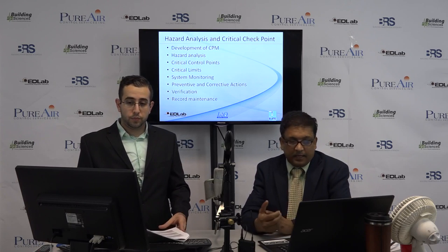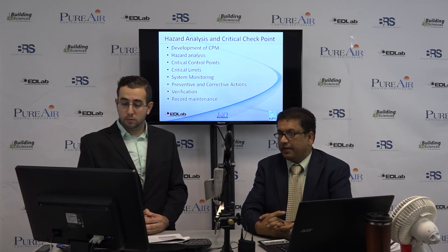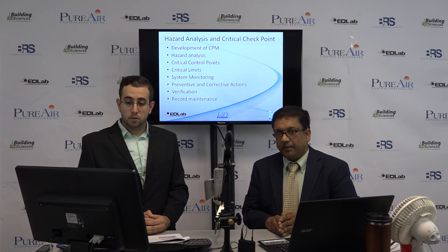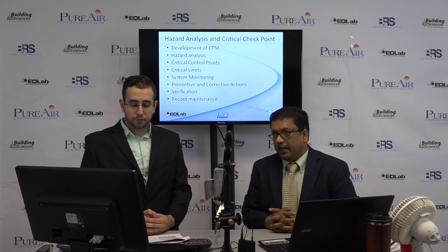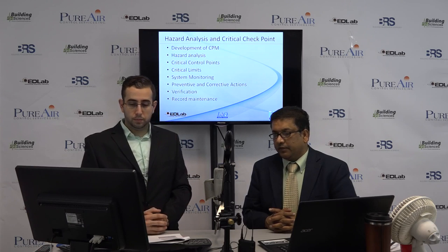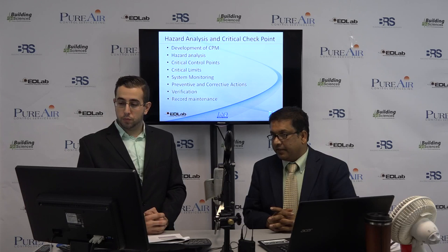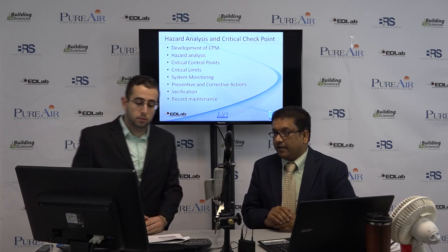So at this point, I want to elaborate on the hazard analysis and critical control points, and this is very, very important. First, I'm not sure how many of our viewers are aware of ASHRAE 188. Basically, ASHRAE 188 gives information on how you should be responding to or managing the water system, so that first of all you prevent or control any risk associated with this bacteria. So truly it tells you the good practices, in a sense, of what you should be doing in order to avoid the problem. That was a little introductory remark about that.